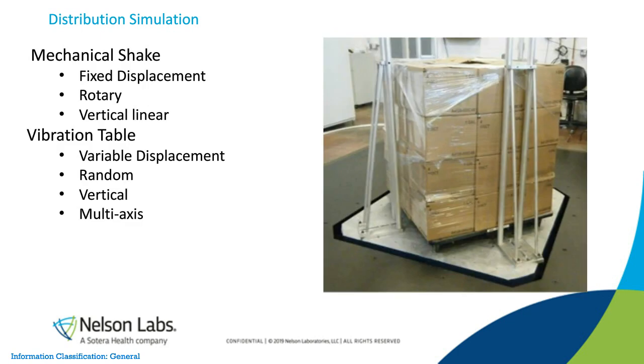Vibration can be rotary or random. Rotary vibration is done with a table which runs a 1-inch displacement circle. This is meant to simulate delivery truck or loose load vibration. The speed or frequency of the table varies per test. Random vibration follows a predetermined set of vibration frequencies. These vibration profiles will mimic long-haul trucks on the freeway or airplanes or trains. The vibration frequency profile is specified in the distribution cycle as well.